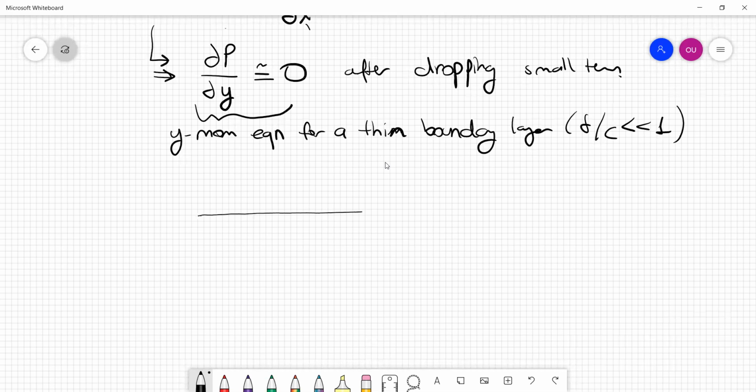So if we have, okay, let's generalize. Let's talk about an airfoil, not a flat plate. Let me delete this. So let's say we have an airfoil, some kind of wing, and let's say we have an attached flow on top of it, so not separated, but a reasonably thin boundary layer growing on its surface, so that the thin boundary layer approximation and the boundary layer equations that we just derived are applicable.